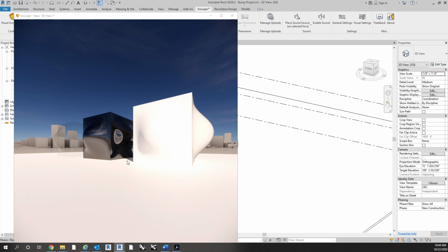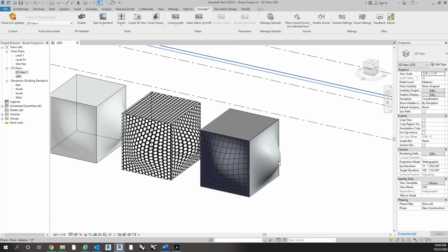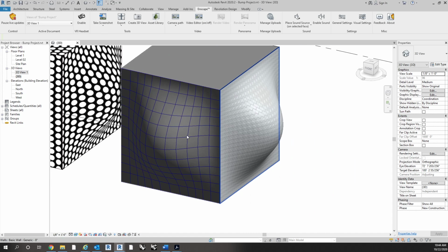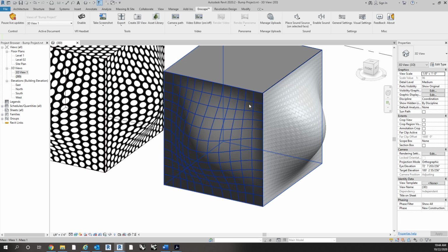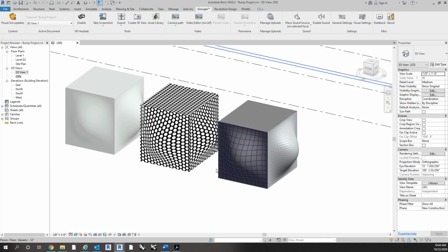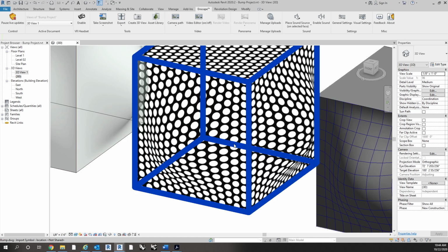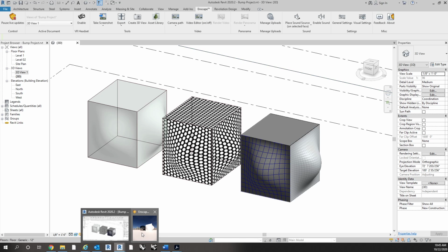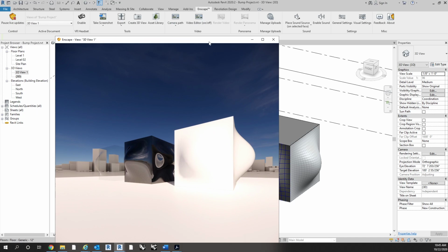And if you can incorporate some of those different elements, those texture maps, within your project, do so. Because obviously, with the cutouts and the bumps and those types of things, trying to model this kind of detail is impossible. It's not impossible. You could do a divide surface that is that dense, but it's going to make your file so large that it's going to be almost impossible to work with. Same thing with cutouts, right? If you did try to model this and cut out all these individual holes, it would take forever. So utilize those texture maps as much as you can, and hopefully Enscape figures it out.